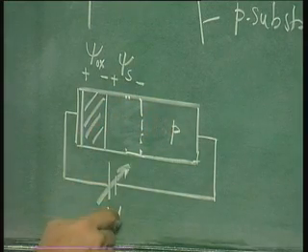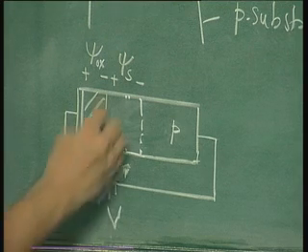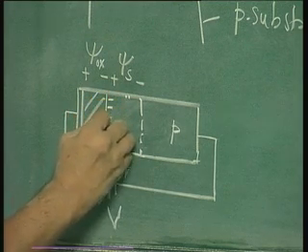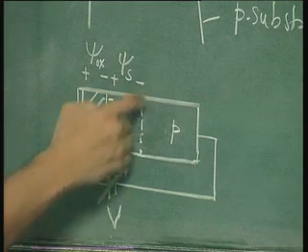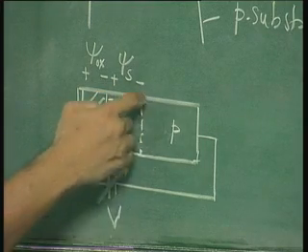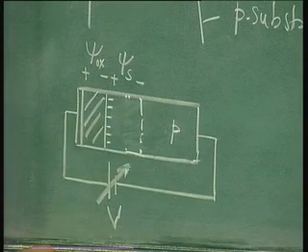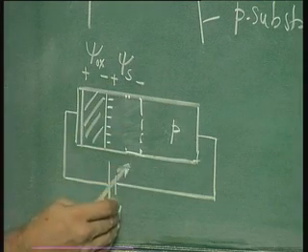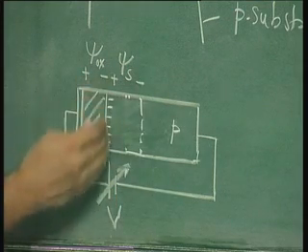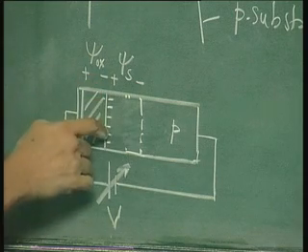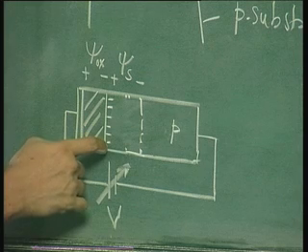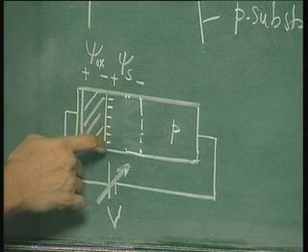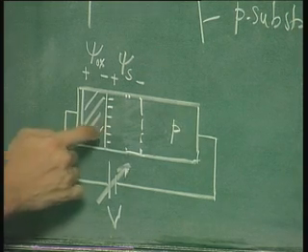When you make an increment, the increment is coming from the charges here, mobile charges, rather than by the increment in the depletion layer or from ionized impurities, because beyond Vt you are getting a large number of mobile charges at the interface and it is easier to get the increment from these charges. Now since the increment is coming from these charges, your capacitance is again corresponding to C0. So this is what we will show here.